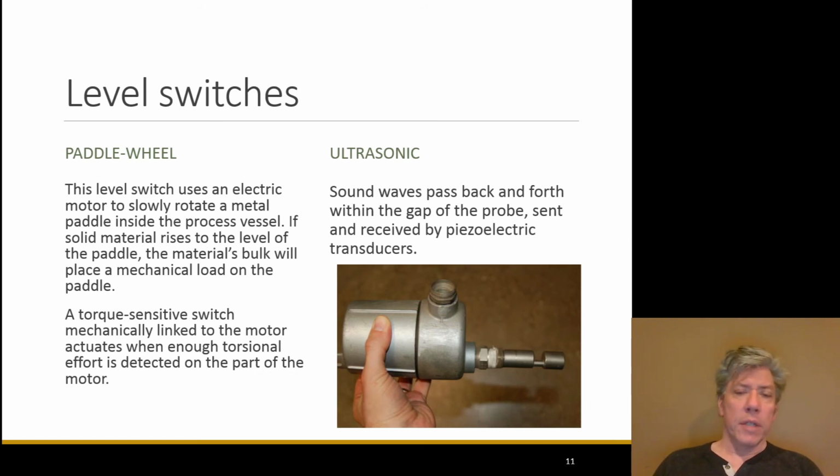A paddle wheel is not a real common type, but it's a simple idea. The idea is that you have a paddle that's slowly rotating inside of a vessel, and when solid material comes up, it increases load on the paddle, and you can sense that.